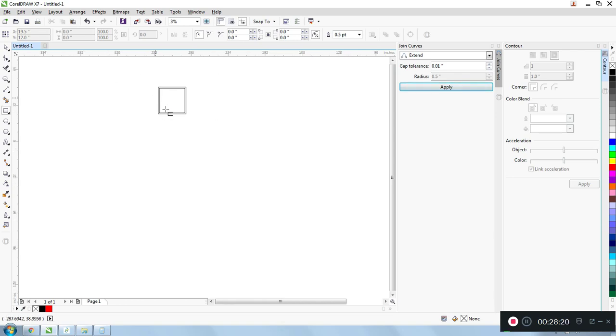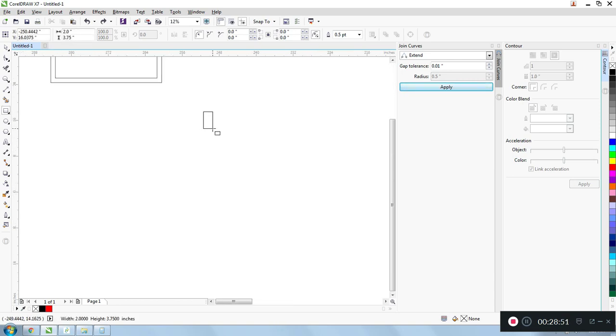So specifically on the CNC router, what we're going to encounter is that we have our slot that we cut out, and then we have our tab that we're going to put into that slot. But because the bit is round, it won't fit in the slot because the corners are not 90 degrees on the inside. They're rounded by the radius of our bit. So we need to solve that,